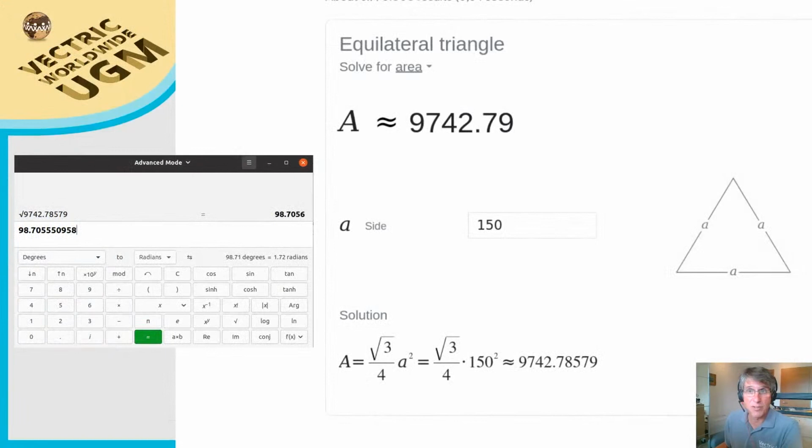It's just the way that you have to work out the area of a triangle. Whenever you put in a whole number like this, you're going to go through this horrible root 3/4 thing, and you're always going to end up with a slightly horrible area. And of course, we need to get back from that area what the equivalent square would be. So here I've just used the friendly Google calculator to work out the area of my 150 mil side length equilateral triangle, which is this horrible number. And that produces an equivalently horrible number, which would be the side length of the equivalent square. Basically, roughly 98.7, and we're not going to worry about it, because we're going to cut this in wood, and the tolerances are going to get a bit crazy anyway.